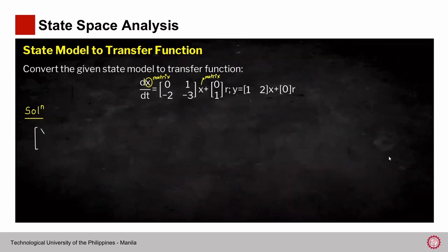So, this is nothing but x1, x2. Derivative, right? dx over dt. It's the time derivative. Then this is the content of our matrix. That's the state matrix: 0, 1, and then we have -2, -3, multiplied by, again, the x, which is a matrix x1, x2. Usual format that we know. Plus, this is the input matrix, definitely. So this is 0, 1.